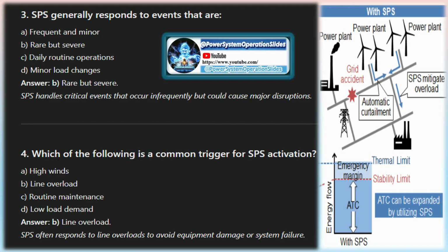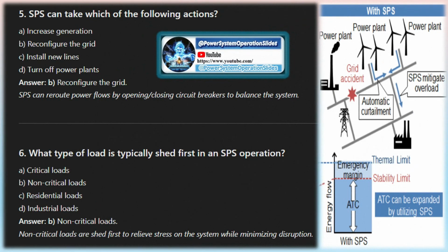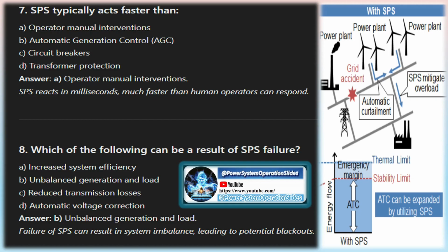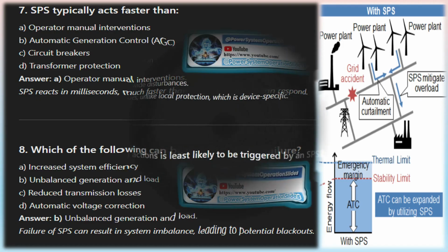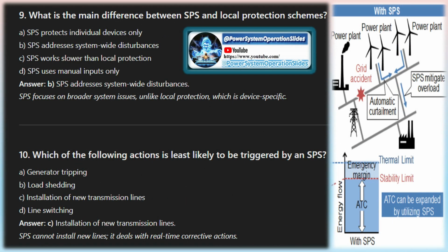Emergency state. As a consequence of contingencies beyond N-1, extreme or unforeseen contingencies, the individual variables that describe the overall system state could violate admissible operational limits and hence the system is considered to be in an emergency state, a disturbed state. A system being in an emergency state might not be able to fulfill its function with respect to consumer supply and power transits, but is not blacked out. However, there is the risk of system collapse mainly due to the loss of stability. Therefore, relevant actions must be taken immediately to bring back the system into acceptable conditions.